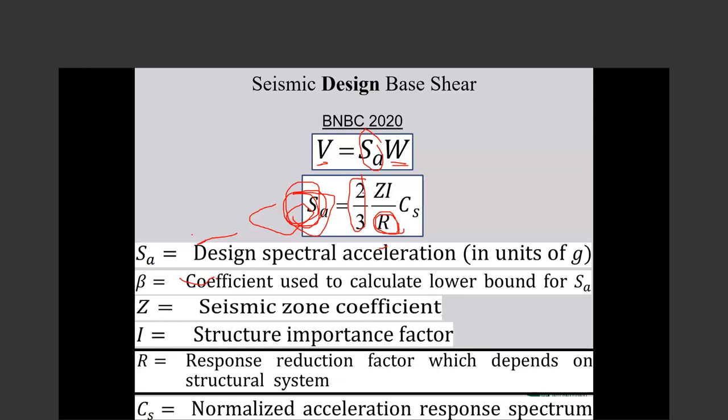But how about looking at the level of those damages? If those damages are acceptable or not for each element, for each response parameter, see if the level of plastic deformation passes the ductility capacity of that or not. But usually we don't do that.